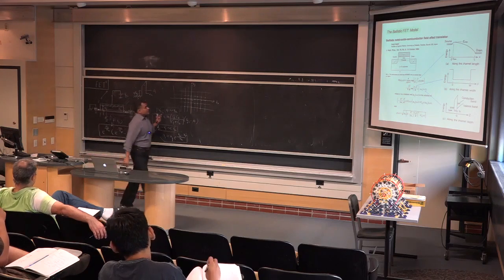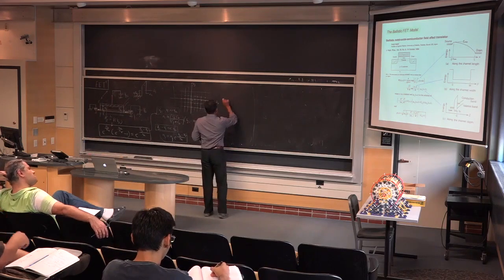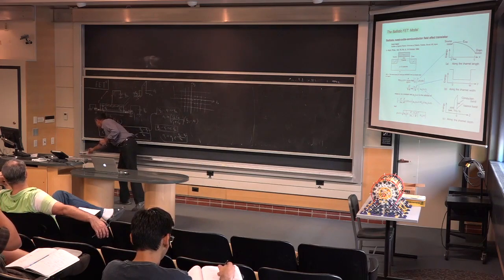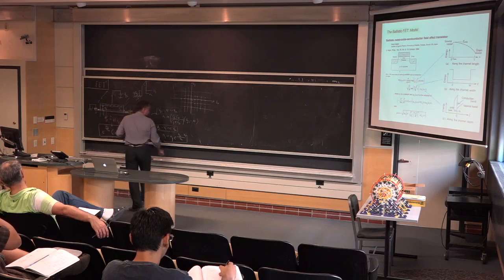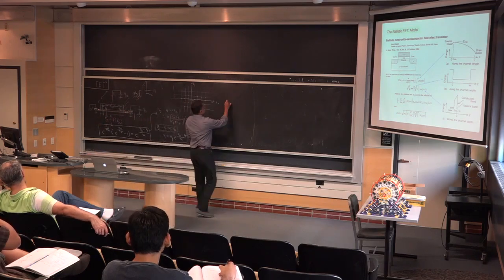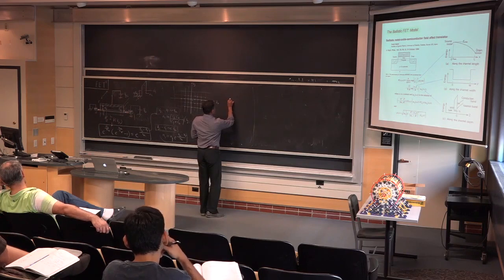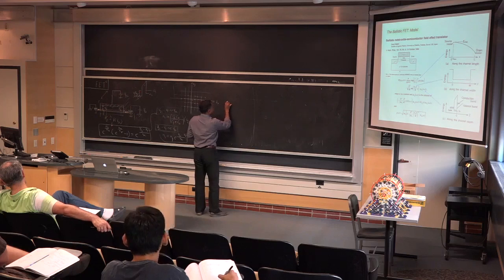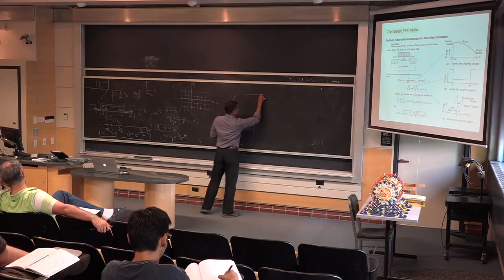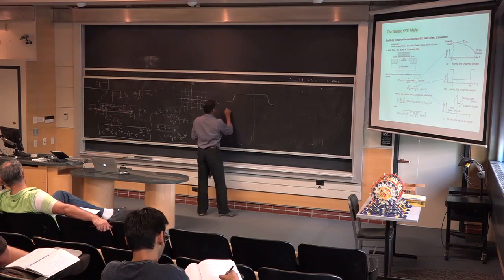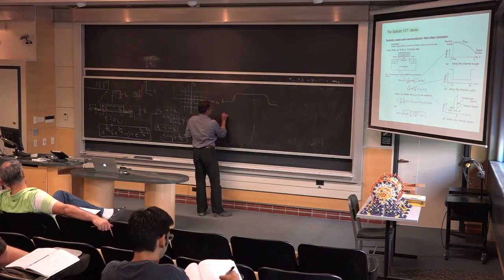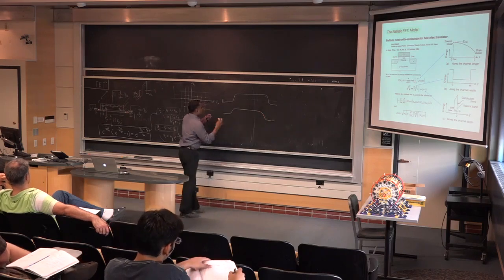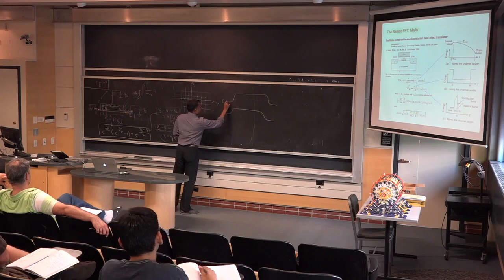And the picture is again something we had drawn, and in fact, let me actually use the colors because this is one place where the color would be useful. So the energy band diagram from the source to drain at zero source drain voltage, meaning when they're shorted, the bands look something like this. This is my conduction band edge, valence band edge, just a gap below it, and band gap.